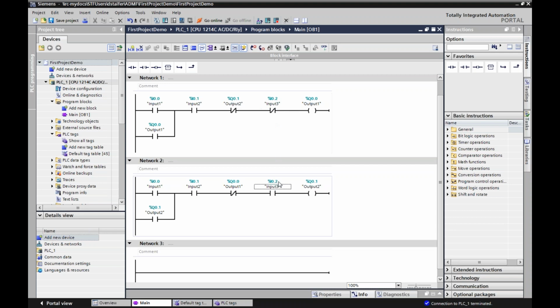So if I have a selector switch that has only got a hot and a low, I could do something that looks like this, and it could still give me one push button to turn on both motors and just make this be my differentiation between forward and reverse, rather than having a forward push button and a backwards push button. Either way works, as I will show you.